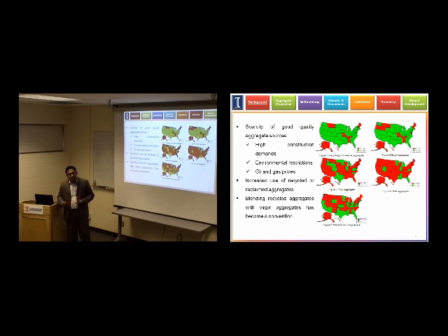But whenever it comes to using recycled concrete aggregates alone in our conventional design methods, we are not picking it up that way. We are blending these recycled or reclaimed aggregates with virgin aggregates for regular design approaches.